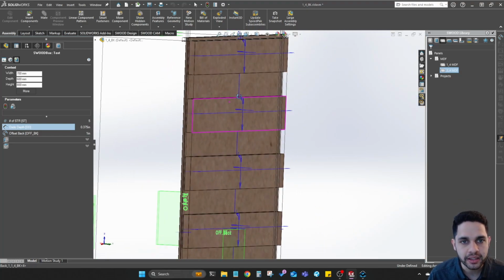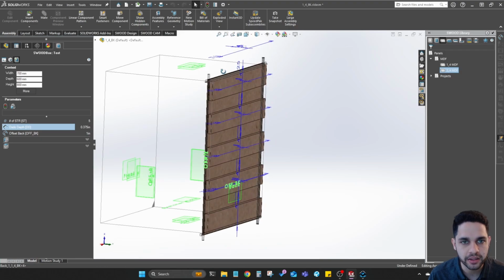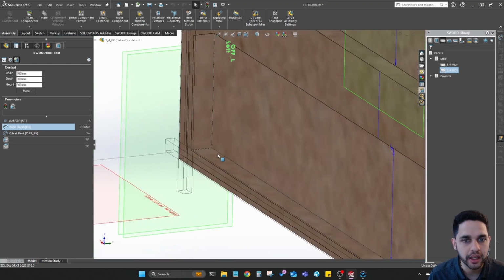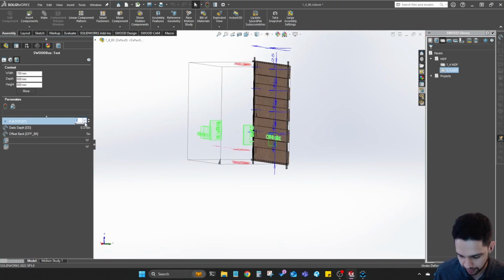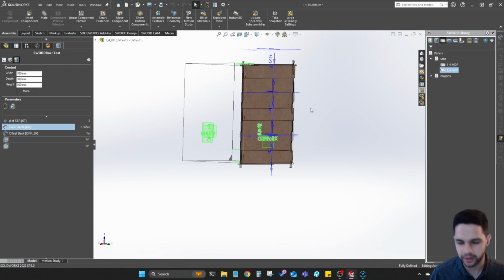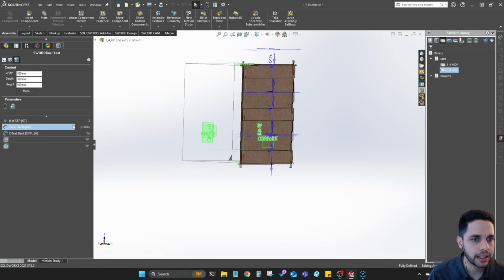And the reason why those stretchers are just being evenly spaced in between those 2 endpoints is because of those reference points that we established in our linear component pattern. So those are definitely really important that you attach those correctly. And I probably explained that somewhat poorly, so I apologize for that. But yeah, so we have our stretcher.